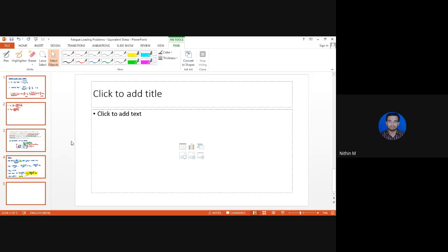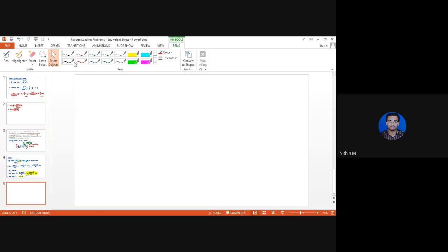Can you tell me the values of KSR, KSZ and KLD? What will be the value of KSR? Again, based on the surface finish, you will decide the value of KSR. Let us assume that it is smooth mill cut. Assuming that it is smooth mill cut, what is the surface coefficient? See how much it comes to. 0.87. Good.